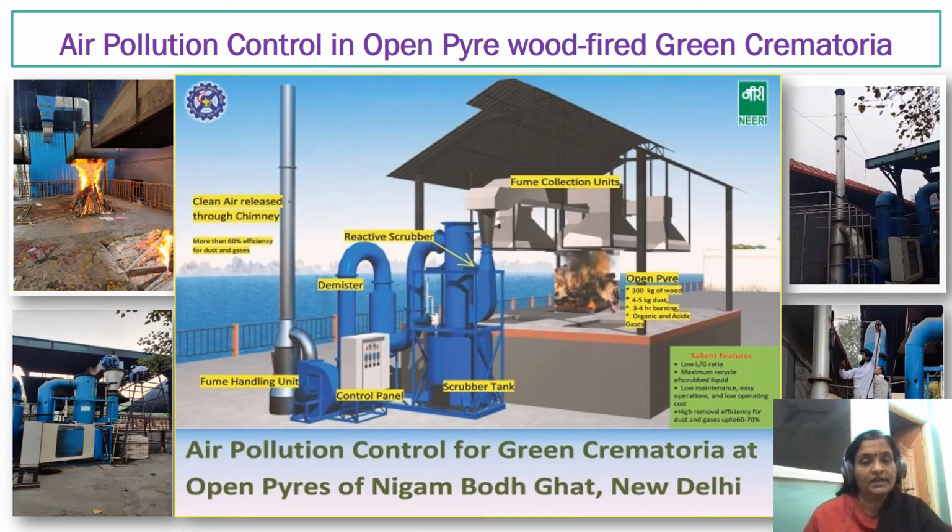Based on that, once we have studied how much gas is to be handled, we have designed the handling system in terms of the fume hoppers, the dust collector and the gas collecting system, the wet scrubbing and the demister systems, followed by the capacity of the blower needed to suction this much gas, and the height of the chimney for safe disposal of the gas.